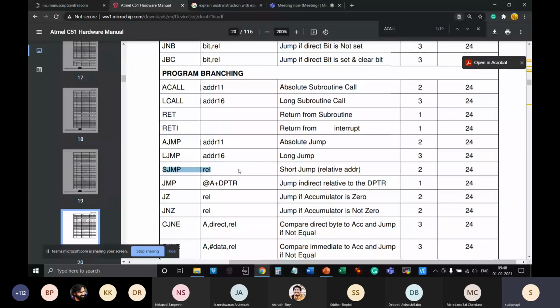This is why I've spent so much time on the instruction set. First of all, the CISC instruction set is slightly longer, and secondly, more importantly, you must have a proper grip on the functions of the instructions. In a microcontroller, I'll give you a top-level summary. You have to understand what is inside a microcontroller, basically the block diagram and the pin configuration, which are the hardware resources. Secondly, what are the instructions supported by that particular hardware? Instruction sets are always customized for the hardware in microcontrollers.